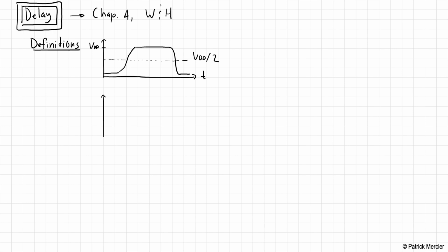Okay, so that's the input waveform. Let's go ahead and look at the equivalent output waveform. Let's say it's going through an inverter. So if it's going through an inverter, the waveform is going to be starting high. After a propagation delay, it's going to go low. After another propagation delay, it's going to go high again, and so on. Again, this is VDD, and sorry, I should label these. This is V in and V out. This is VDD. We'll draw a line through the middle here, and this is VDD by 2.